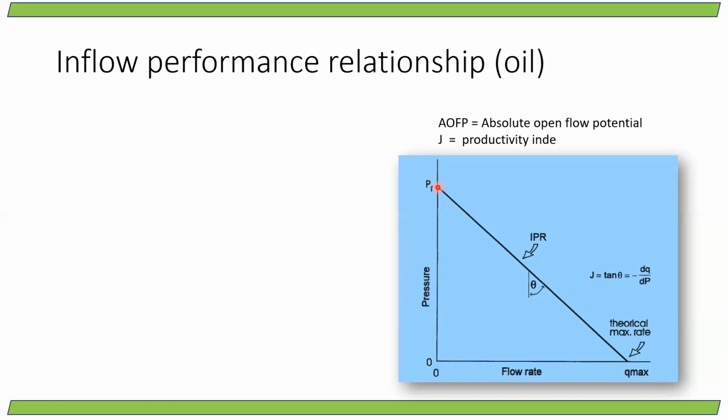Inside your reservoir, when a well is drilled, it will have a drainage area. Beyond the drainage area, the pressure is equivalent to reservoir pressure. Near the wellbore, the pressure is wellbore pressure. Only the pressure difference makes oil flow from high pressure to low pressure. It's like diffusion from high pressure to low pressure. So the reservoir pressure should be high and the wellbore pressure should be lower.